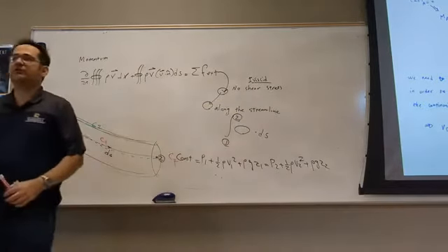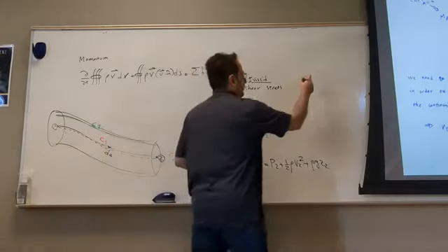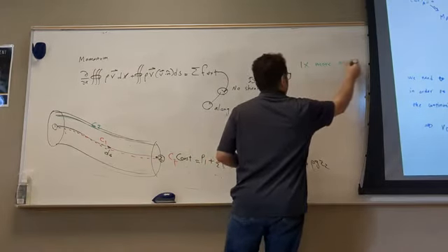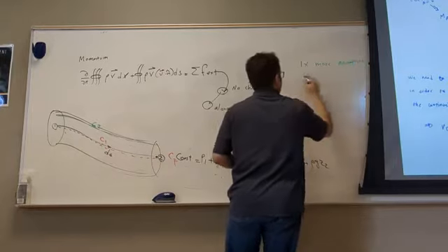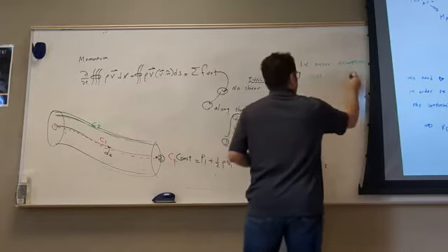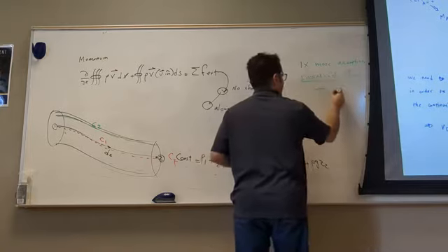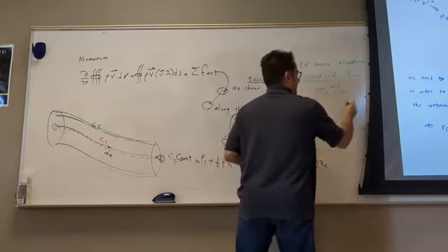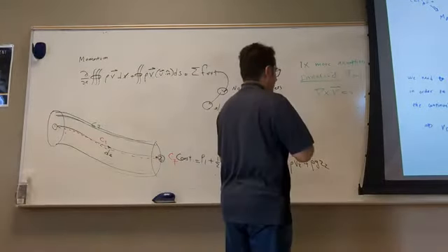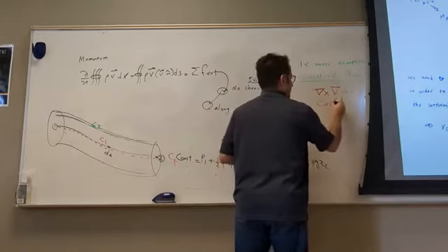In the energy equation, we make one more assumption. So the only assumption here is inviscid. If you make one more assumption, and that is irrotational flow. Mathematically speaking, curl of velocity is equal to 0. So what does it mean? First of all, do you remember this operator in calculus, curl? Curl of a vector field, they call it curl. Do you remember that?